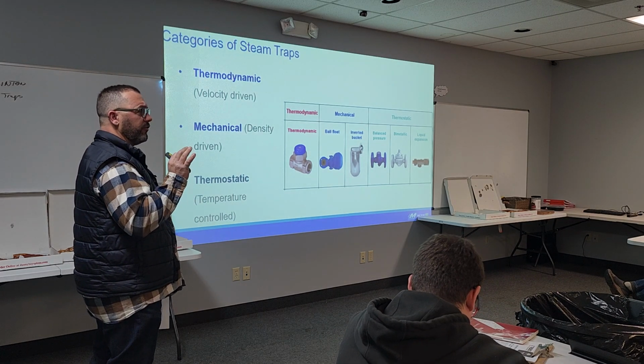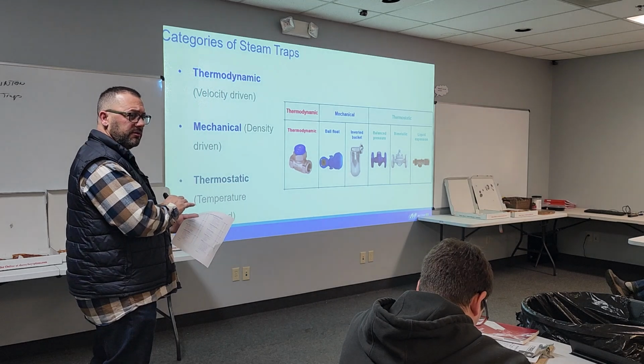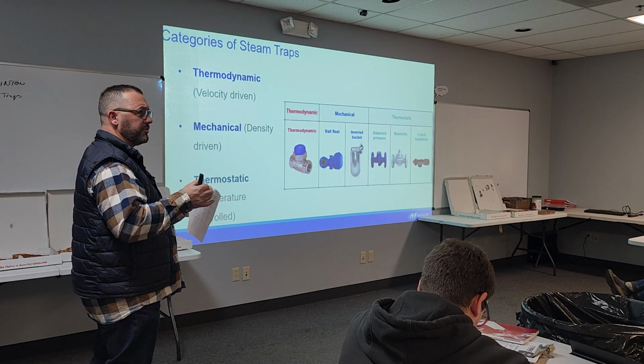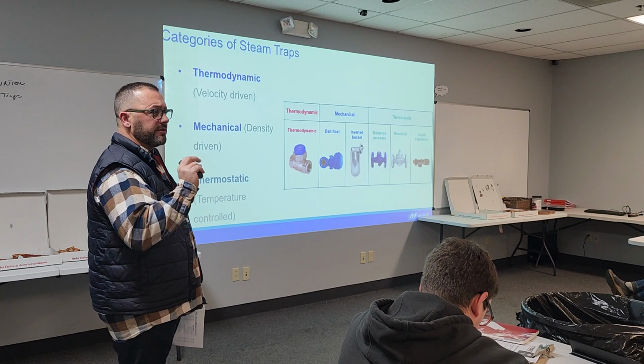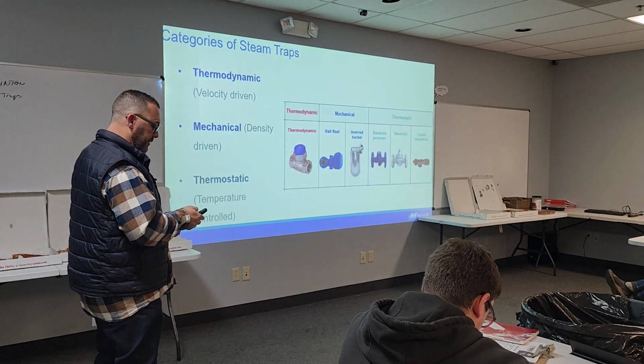The bigger the orifice, the lower the pressure. The higher the pressure, the smaller the orifice. So that's really what changes in those traps, the size of the orifice.